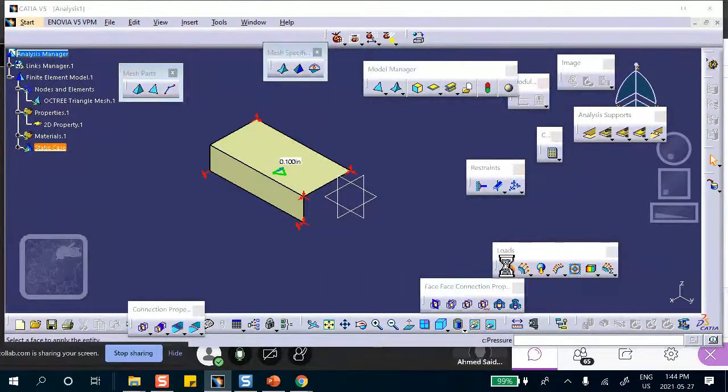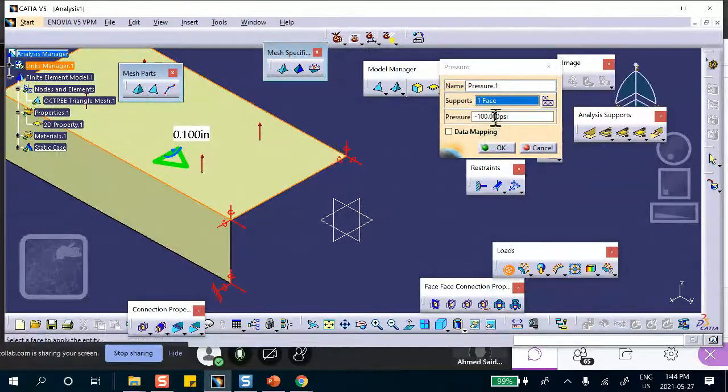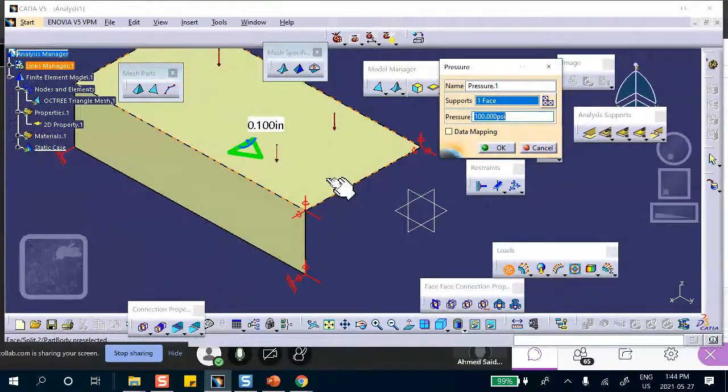Okay, pressure on the top face. Make sure the direction is correct. Look, this time I have to change that thing to 100, because when these surfaces are extracted and you join them, you don't have control over what the direction of the join is. In the previous one, I had to put a minus. This one, after the extraction process, I had to take that minus off. But the direction must be correct, and this is correct. If I put a minus sign here, it won't be correct. You're pressurizing it from the bottom.